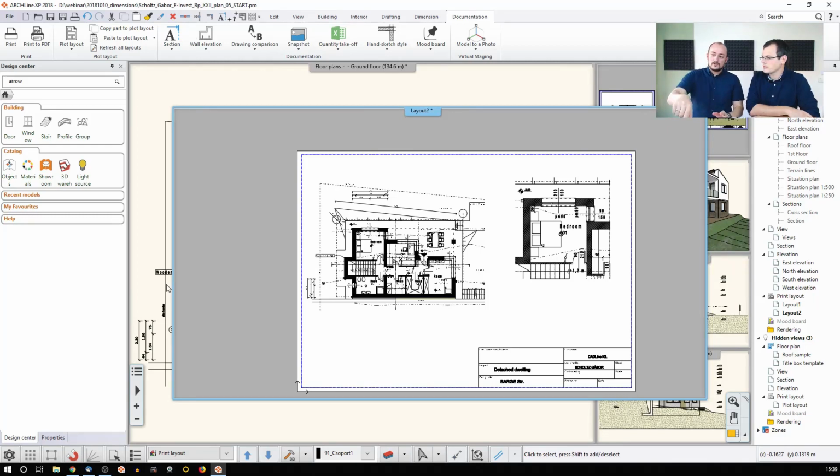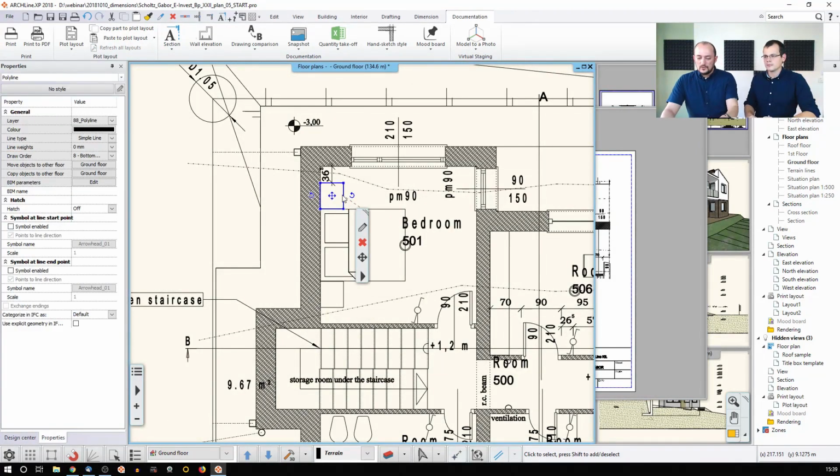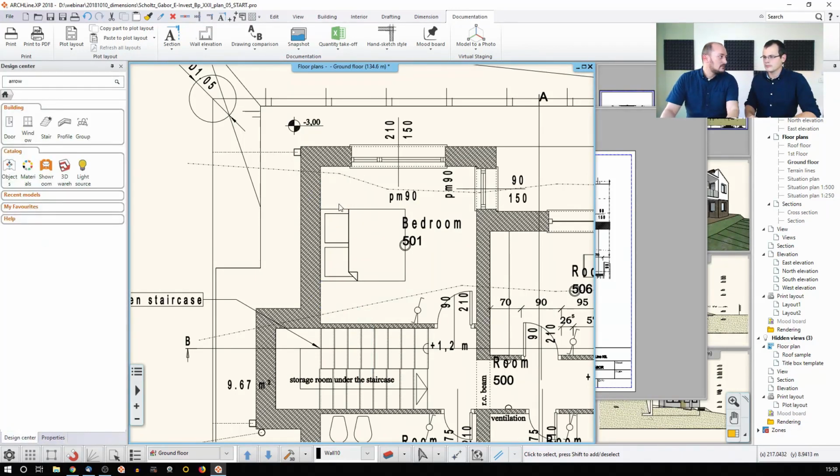And whenever I change the original content, I will show you that the software will reflect those changes, and it will actually update when I say so. It will update the content. Let's just do something like that. Okay, I'm about to remove this here and this here. See that dimension also disappeared because it was linked to the item. Right, I actually erased them. I don't want to see them because we changed our minds.